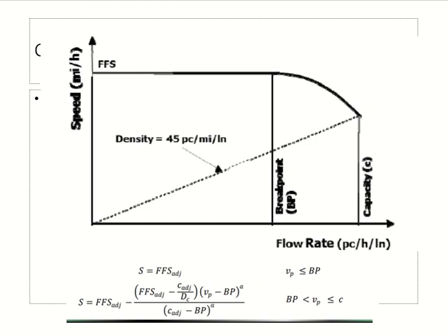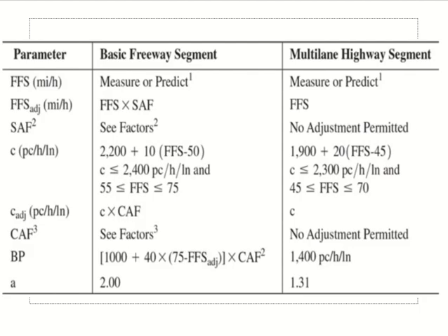Yeah, it can be free flow speed. It may not be. Okay, how do you decide? Based upon breakpoint. If you are behind breakpoint, then you have free flow speed. If you are in front of breakpoint, then you have speed which is less. So I need to decide whether I am before breakpoint or after breakpoint. Okay, breakpoint equation. This one.